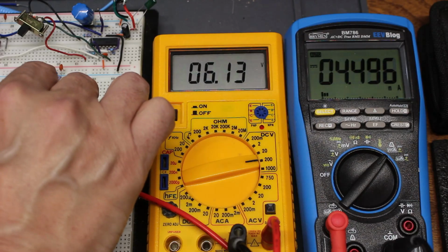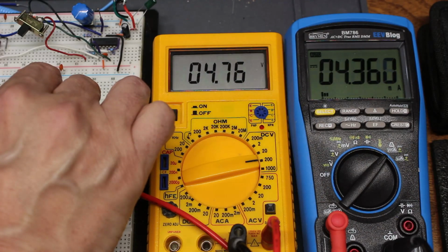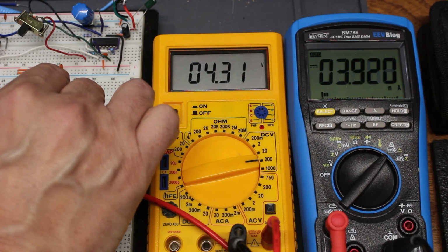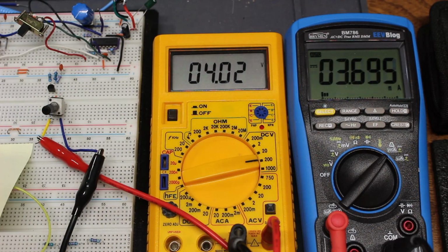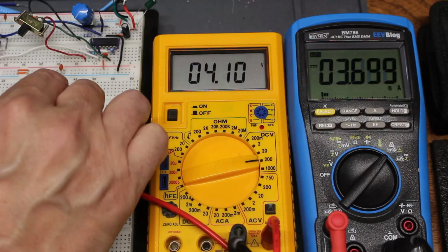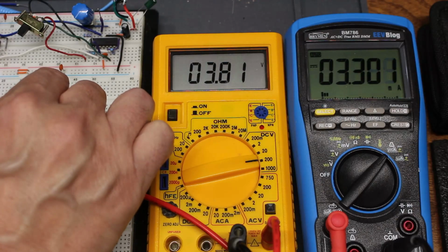But as the pot comes closer to mid-range, the current starts to fall off. If we look at the collector voltage, what we see is that the resistor is now so high that the voltage drop across it has the collector down to 4 volts. The transistor is a valve, not a pump. It can't pull its output significantly lower, so it can't provide any more current.